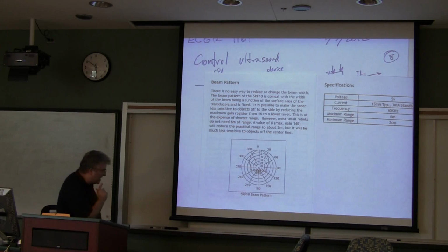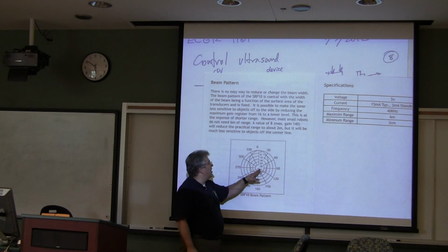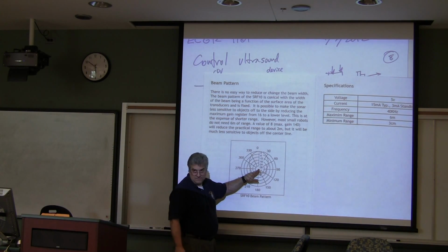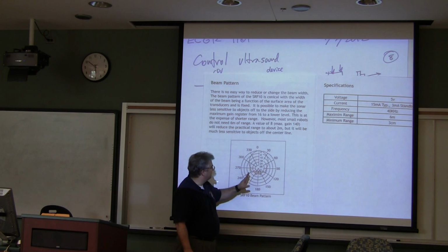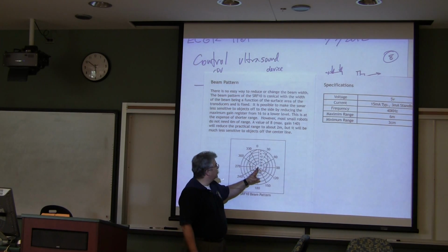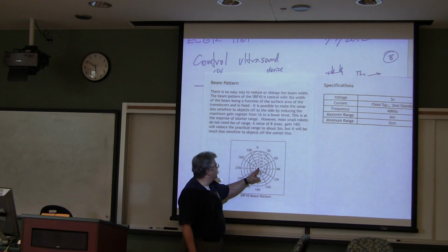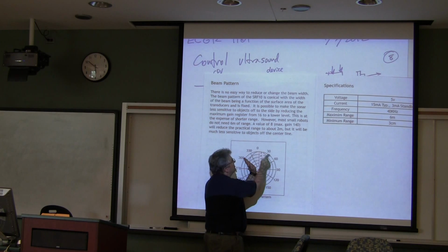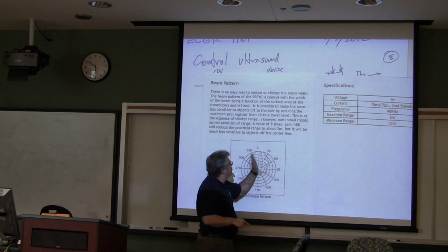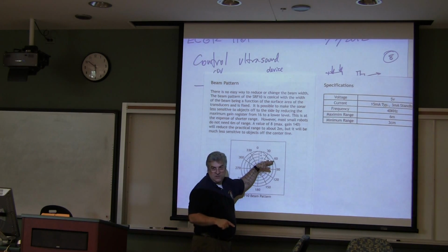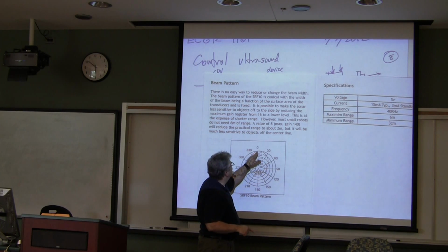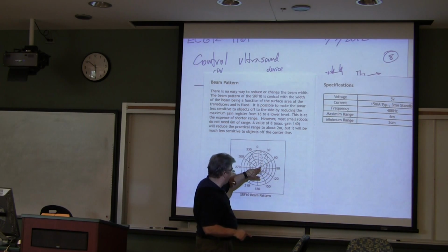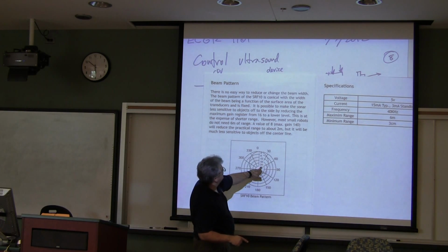What it is saying is that if this is the center of your transmission, it does a good job of detecting devices or other things in its way between these angles here, which look to be about a nice 120-degree field of vision, and then its distance looks to be about 30, and I think this is 30 centimeters.